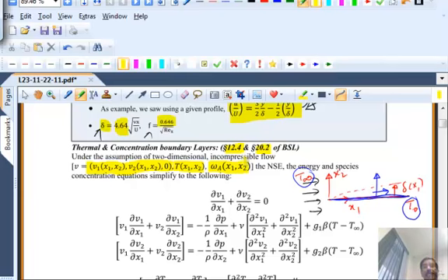So the omega A here is the mass fraction, for example, of a particular species. Here you have to think of the plate as being made up of a naphthalene sheet, for example. Naphthalene can sublime into the air, so you'll have mass transfer by sublimation. Or you can think of that plate as being coated with a thin film of methanol or ethanol or whatever material that can evaporate.